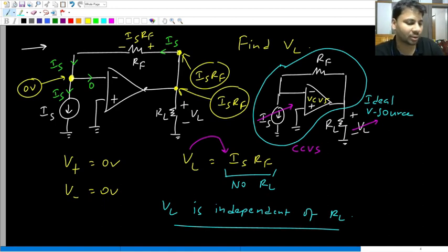Of course, in all the circuits we have negative feedback. So you can generalize this discussion and make a statement that if you have one type of dependent source, it could be any dependent source, then by using proper negative feedback, you can always implement any other type of dependent source. That is the power of negative feedback.